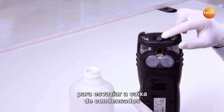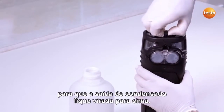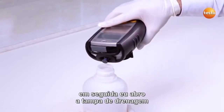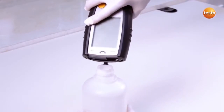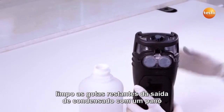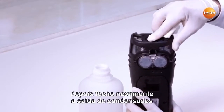To empty the condensate trap, I hold the measuring instrument upright so that the condensate outlet is facing upwards. Next, I open the drain plug and channel the condensate into a collector. I dab off any remaining drops on the condensate outlet with a cloth. I then close the condensate outlet again.